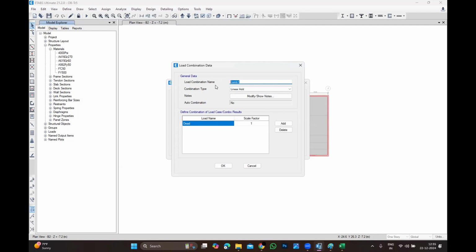The 30% is straightforward, because you reduced your vertical elements by 30%, right? The same 30% will have an impact, because your structural lateral stability system is the vertical elements, not the slabs, not the beams. The pure vertical elements could be columns, or shear walls, or a combination. It is either called a building frame system, or a shear wall system, or a dual system. Only three systems you have.